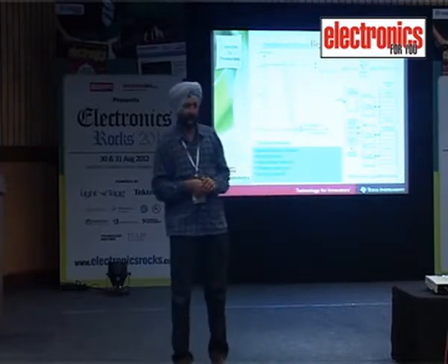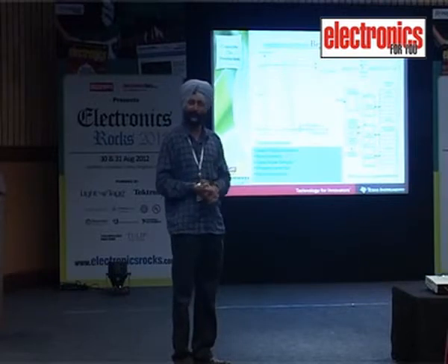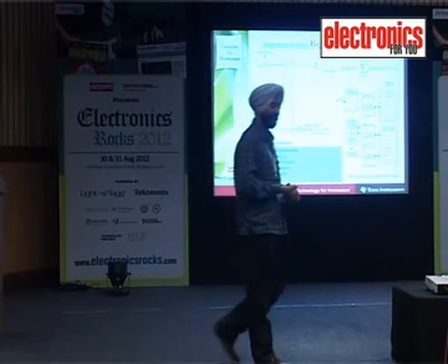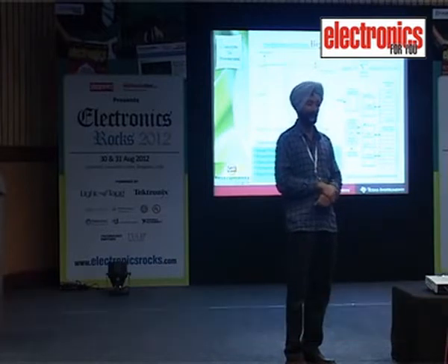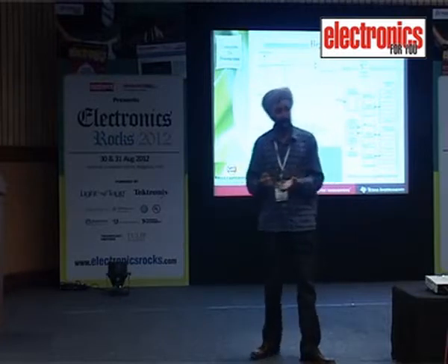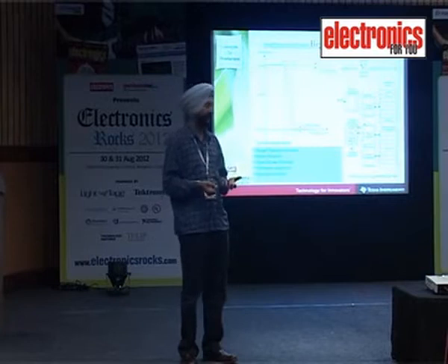Maybe there is no sound for heartbreak, but definitely there is a typical sound for glass break, right? Now for a glass break, you just need a sensor. What kind of sensor? Just a 2 rupees sensor, a microphone. And you have built-in amplification in MSP 430 where you will be able to amplify the signal from the microphone. And then what else?